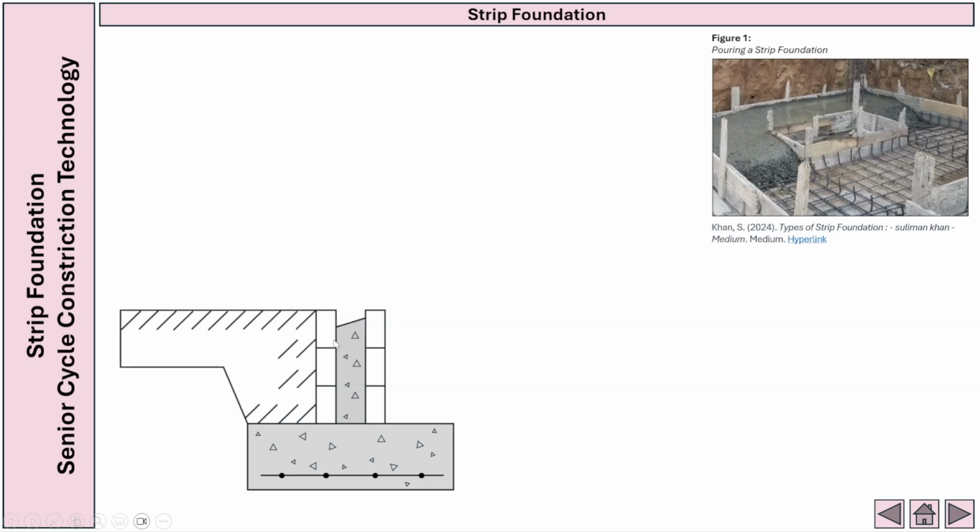The next thing, we're going to head on over to the left and we're going to draw in the ground. So this is the ground on the outside of the wall. The total distance between this line and this line is 600 millimeters. So all I've done is I've gone up 30. I've got my 60-degree set square, just went up at 60 degrees, and I went out just a non-specific distance, I'd say about 50 millimeters, up 30 again, and then just brought it straight across to meet the cavity wall here. Then to show that it's just an outside ground, I just drew in a few lines here, and these are just 45-degree lines. You don't need to fill in the whole box, just fill in a couple there on the side.